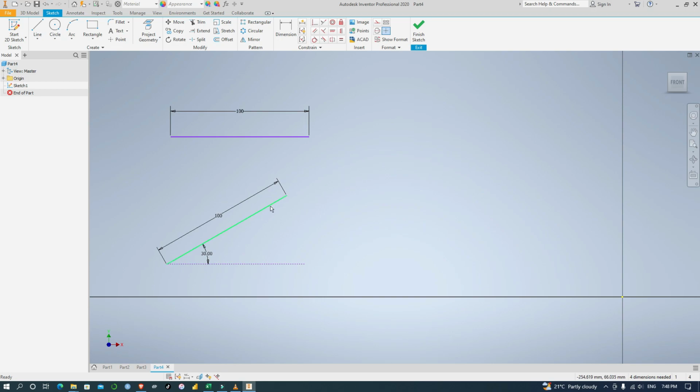If you want to turn it back to the horizontal, you move to this section and you click horizontal, and then I'll click this line. Cancel. So you find that it has refused to move to the horizontal because of this dimension. So let's remove the dimension. We first remove the dimension, and let's remove also this. Yes, now we try to make it horizontal and see what will happen to it. Yes, it is now horizontal. That is how you change a line to a horizontal or draw a line at an angle that you need. So let's delete the line.